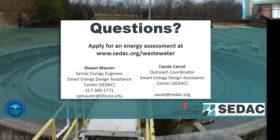We did have someone in the chat ask a question. Have you seen VFDs used on exhaust fans to control velocity based on wind conditions? I have not seen that, but it does bring up a point for ventilation systems. One recommendation that we have offered for a couple of plants that didn't have it is hazardous gas detectors to control ventilation rates.